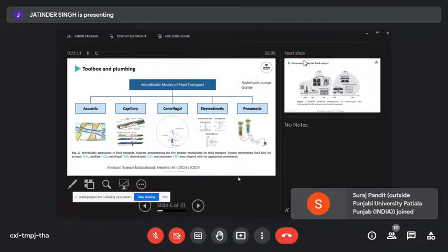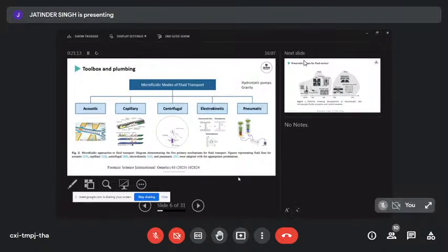We can do things by capillary forces, capillary actions like the wicking of paper that we'll be seeing later on. I think this was the lecture when I went over time, that you got spared a whole range of physics. But capillary forces, we've all used a straw to have a drink. You know that the liquid is creeping up the sides of the straw. You can fill a microchannel with it. So capillary forces are really good to get your channels filled with liquid, get them primed, provided you're working